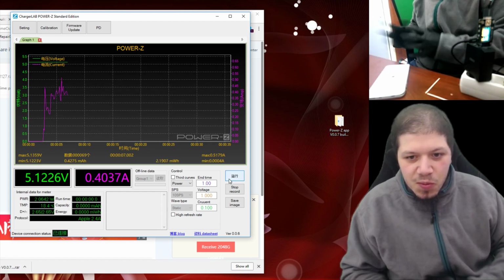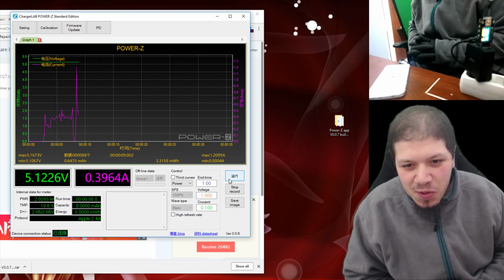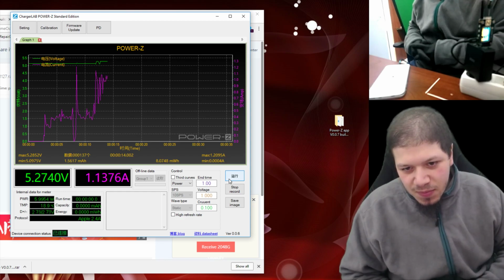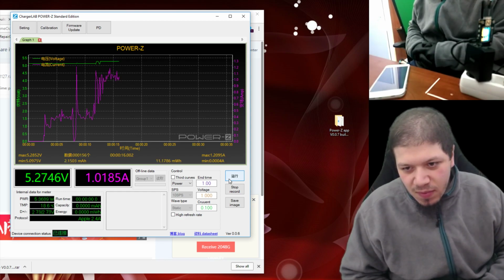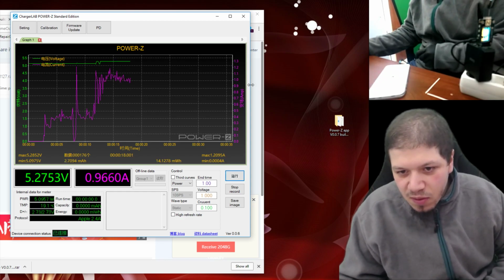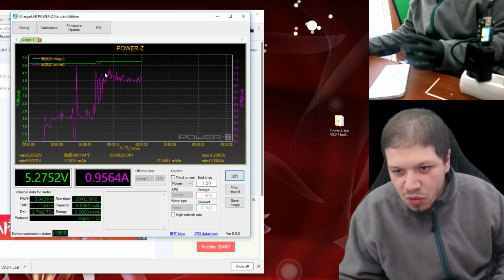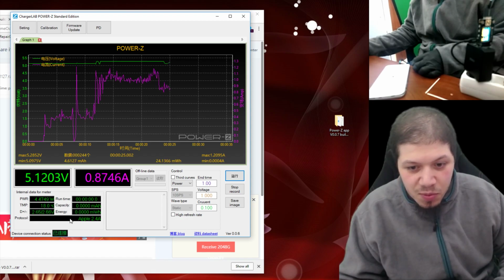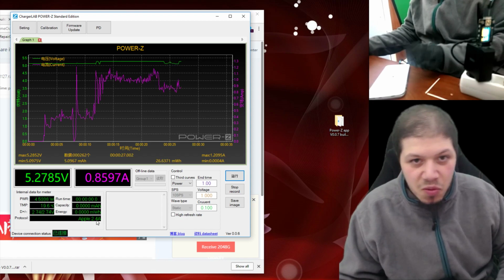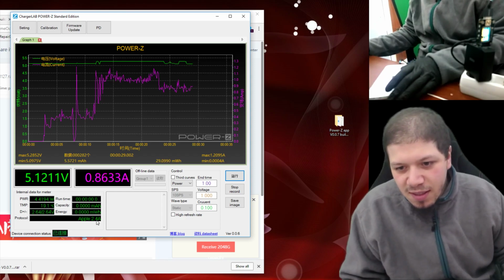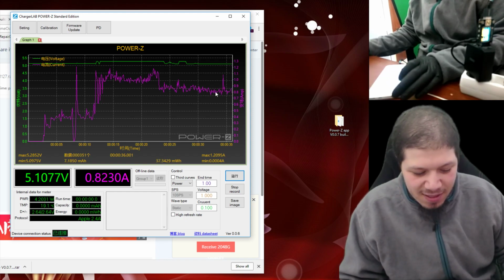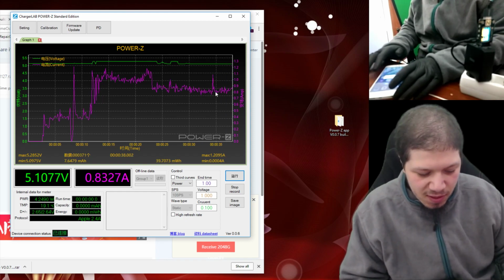And it should show you the power up power consumption of the iPhone 6 Plus. You can see it goes right to 1.1, 1.2 amps, so it tells me it's very good. The protocol is Apple 2.4A, so it recognizes it, so maybe TriStar is good. And this is a working phone, by the way, so this is the normal behavior. Okay, so now the phone has fully booted.